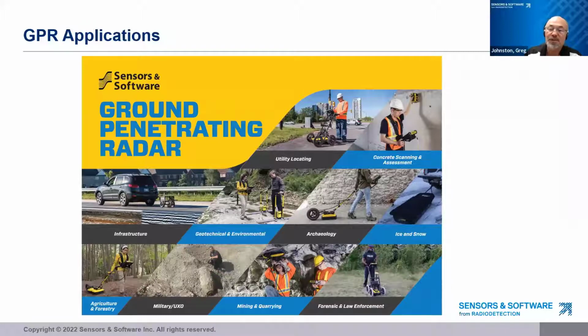The more typical use of GPR is to find buried utilities for construction. Remember that one of the strengths of GPR is that it can find non-metallic objects, and many modern utilities are made of PVC, plastic, concrete, fiberglass, and other non-metallic materials.